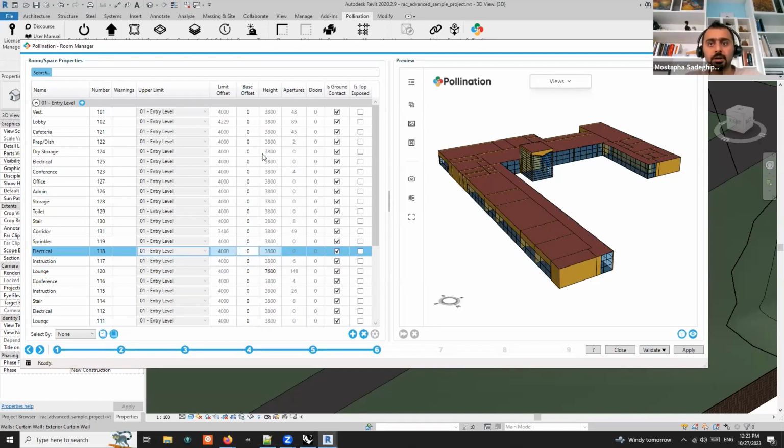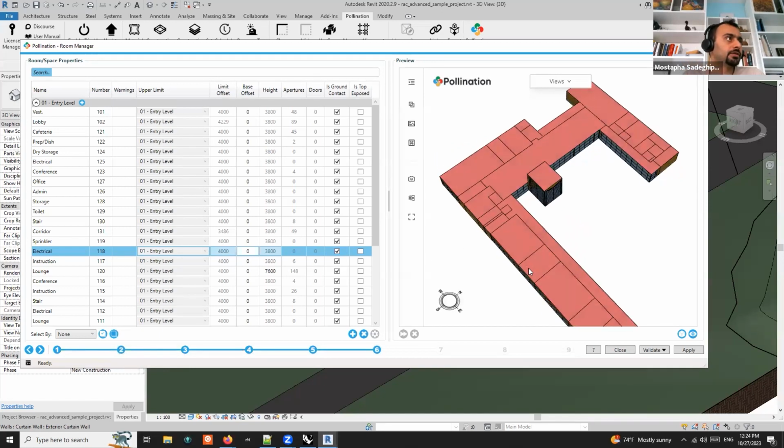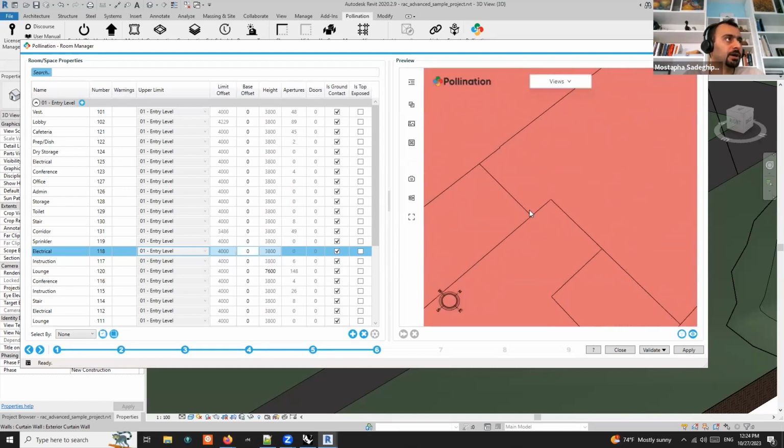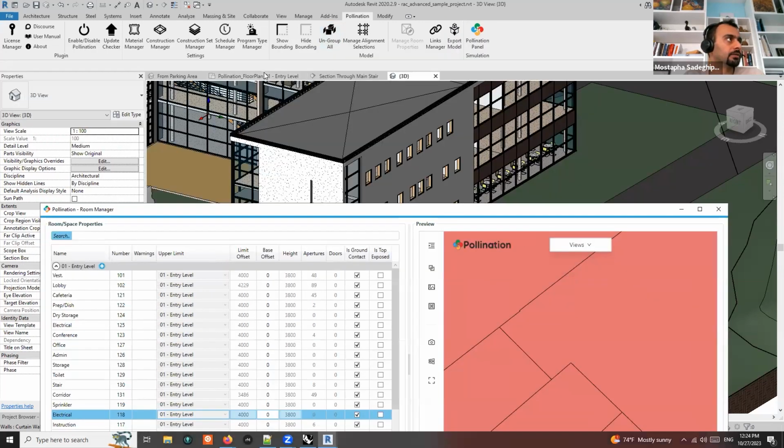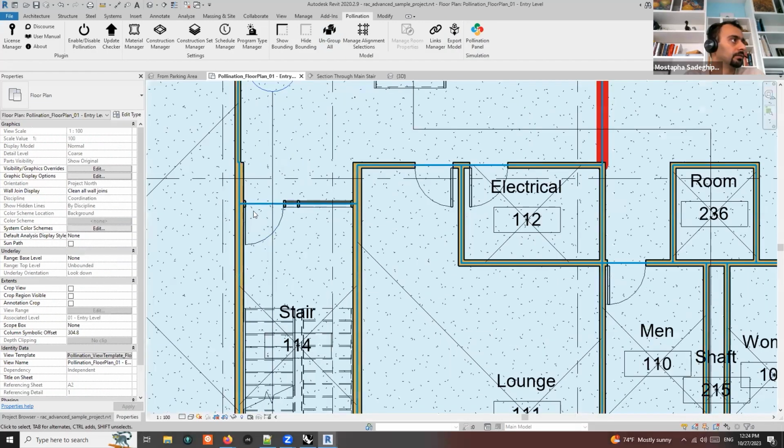Good question. Any other questions? Mustafa, did you answer Ibrahim, who was wondering about a small gap between two of the rooms? Right, so there is a separation line there, Ibrahim. I think some version of the sample model has another separation line. So if you see a small gap between these two rooms, there is an additional separation line there that you have to remove. You see two separation lines here, right? If you just remove that separation line, then it should be fixed.